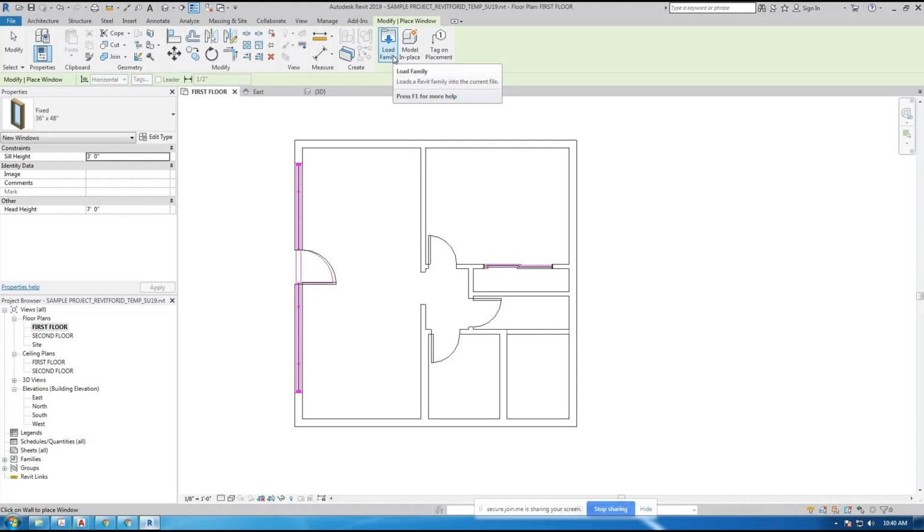And if you open up the family, you can then bring in those products into your project. So this command is not isolated for Revit. You can actually use it for any manufacturer. And it's for anything you can think of, doors and windows, but also furniture, light fixtures, casework, any type of material you want to use from a manufacturer. You can visit their website and see if they have Revit families available, and those families can be downloaded into your project, especially appliances and things. Just be careful that sometimes those project families are huge file sizes. So just make sure you save your project before and take a peek at it afterwards to make sure it's not gotten too big.